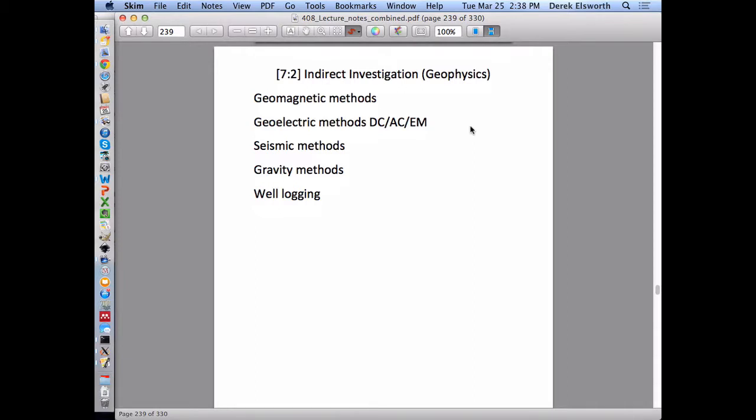If you don't put instrumentation in, you might want to seal it with something because you don't want to leave aquifers that are interconnected. In fact, when people talk about CO2 sequestration, apart from this class, a big picture question for them is that if you go into pre-existing petroleum reservoirs that have been depleted and use those as the place where you'll store the CO2 so it doesn't go into the atmosphere, so burn it, take it out of the flue stream and push it underground, one of the egress methods for that, perhaps the largest one, is fugitive emissions along pre-existing unplugged boreholes.